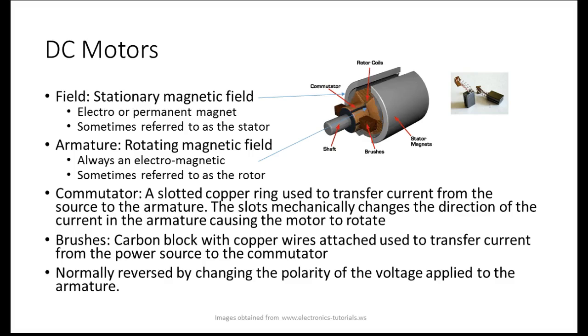So if I've got a 12-volt DC motor, I put 12 volts on that. How do we cause one of the fields to move? We let the motor cause it to move, right? On the back of it we have this unit called a commutator, which is made up of different slots. When it turns, here comes the power, so we have to have a commutator and we have to have brushes. I put DC on the brushes, the brushes connect to the commutator, and the commutator connects to a bunch of coils of wire, which makes an electromagnet.